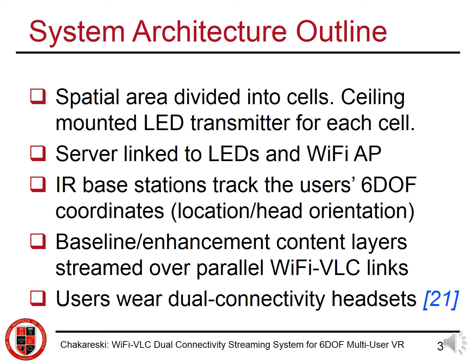There are two IR base stations that track the user's 6 degrees of freedom coordinates, and there is a baseline and enhancement content layers streamed to each user over parallel Wi-Fi VLC links, and the users wear dual connectivity headsets.